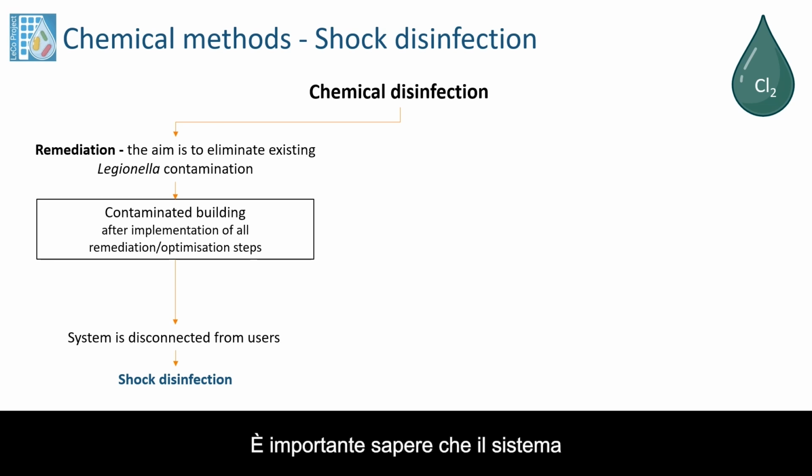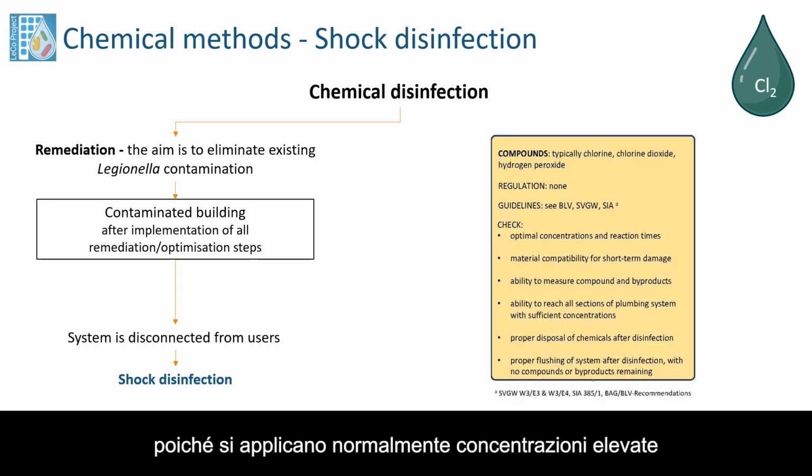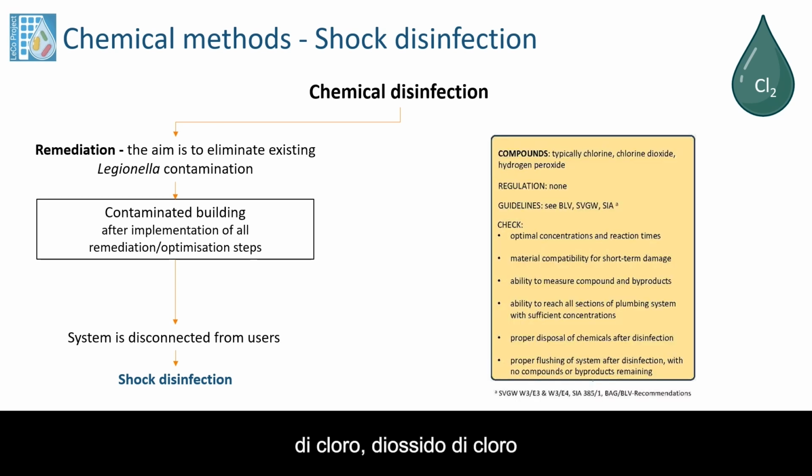Important to know is that the system is disconnected from the user. Typically a high concentration of chlorine, chlorine dioxide, or hydrogen peroxide is applied, and as it is disconnected from the user, there is no direct regulation on this. However, there are guidelines on how to apply it.